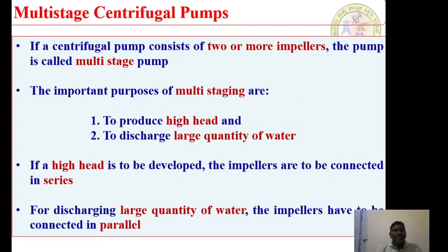The next topic is multi-stage centrifugal pumps. It's a very important concept. There are two important purposes for a centrifugal pump. A centrifugal pump has to discharge more volume of water, and it also has to raise the pressure head to a particular magnitude. So both performances have to be carried out by the respective centrifugal pump.